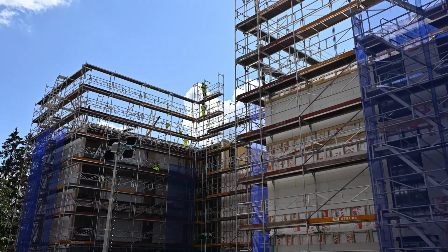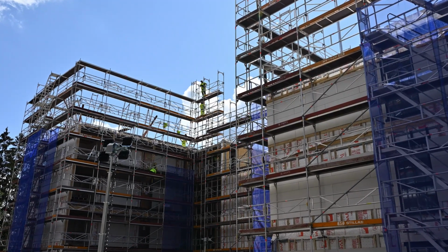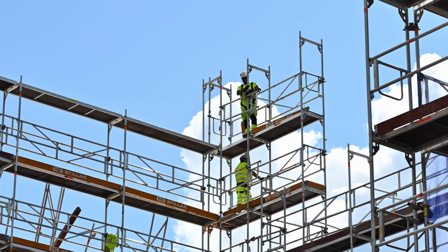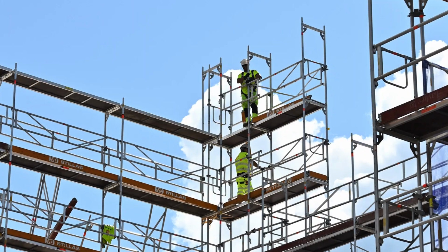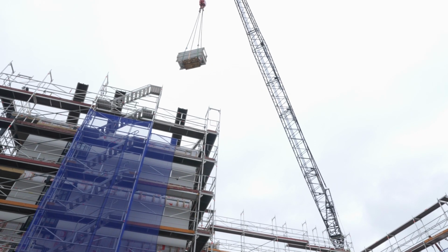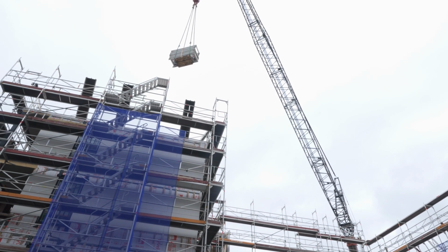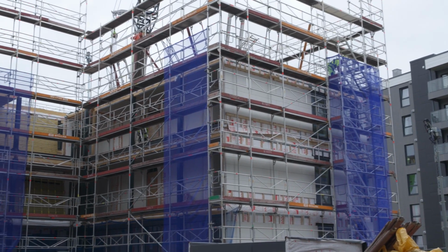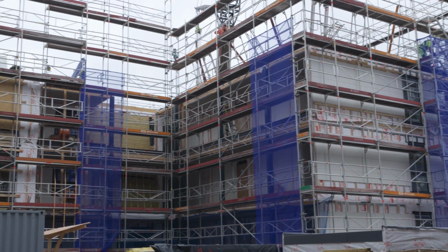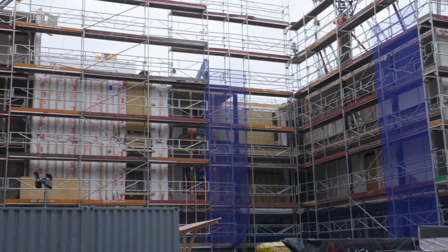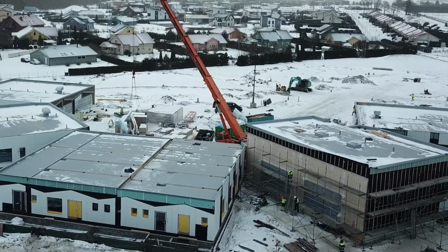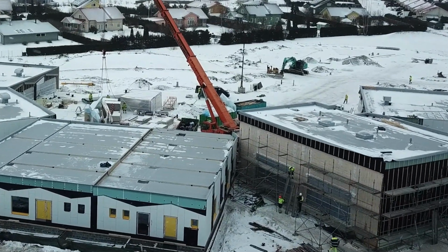A safety factor that always requires special attention is the risk of falling from heights, but there can be various hazards on a construction site. For instance, the installation of scaffolding can occur simultaneously with the erection of the building, with scaffolding being installed on one side while modules are being lifted on another. This can easily lead to a situation where the zones of different works intersect after some time.